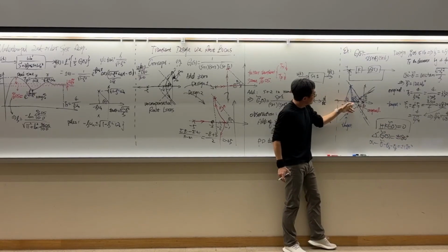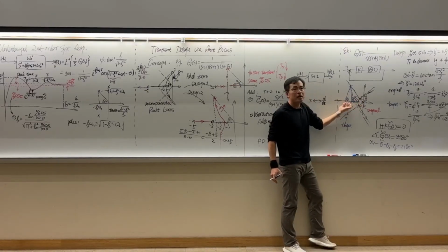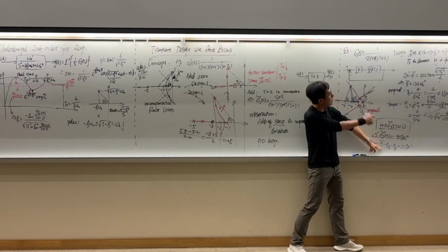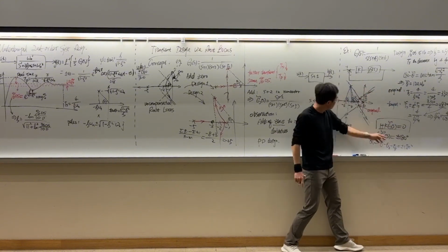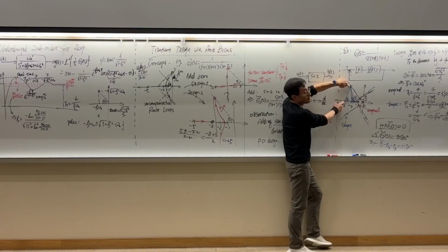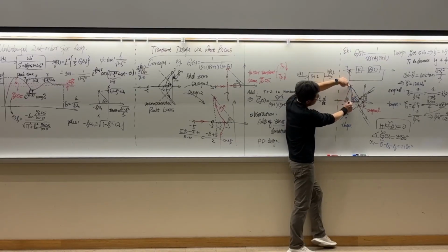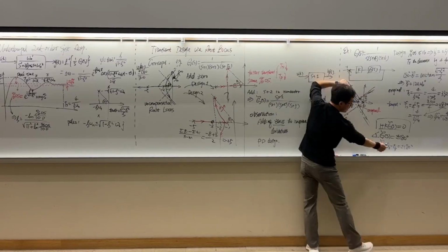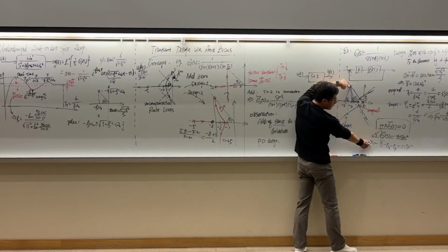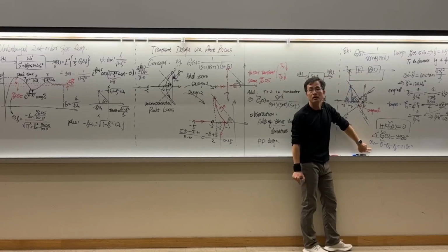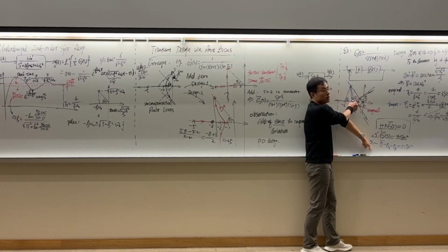You can read many of these. Theta tilde we already calculated, 120.26. And then theta 2, you know the location of this one, so you can read theta 2 from the graph. Same thing, you can read theta 3 from the graph. So these can be read out from the root locus plot. Then you will know alpha 1. You will know the angle, and you know the open loop zero you should design. That's the concept. Any questions?